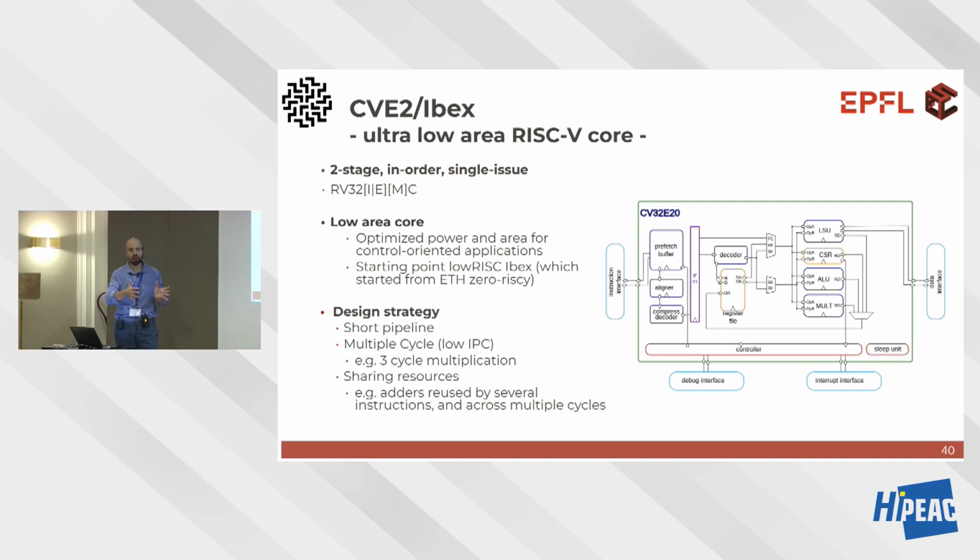Could be that the first part is the second half of the previous instruction, or the first half is the instruction itself, the whole instruction, because it's compressed, or it's the whole 32-bit instruction. You don't know that. So are 32-bit instructions allowed to start at a non-4-byte offset? Absolutely, yes. Otherwise, you won't have any advantage, right? Because otherwise you waste. It's true that they are compressed, but then you waste 2 bytes. So it will be the same, right?